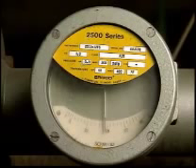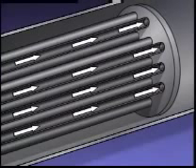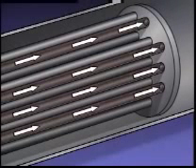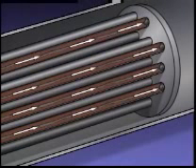transferred also increases. Heat transfer can also be affected by the presence of contaminants in the fluids. These contaminants, or impurities, can build up on a heat exchanger and form another layer of material that the heat must transfer through. This layer of material will act as an insulator, and the amount of heat that can be transferred in the heat exchanger will decrease.